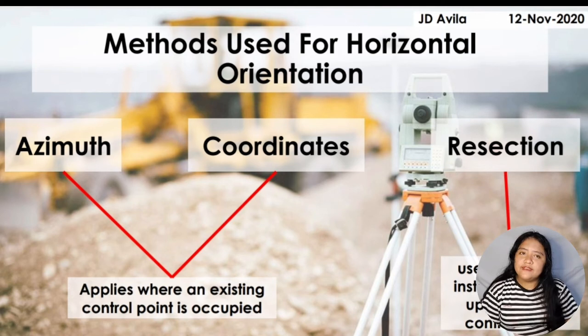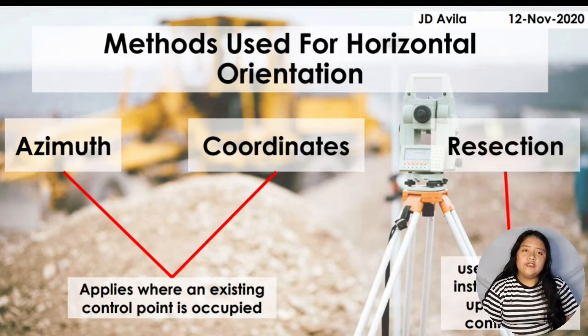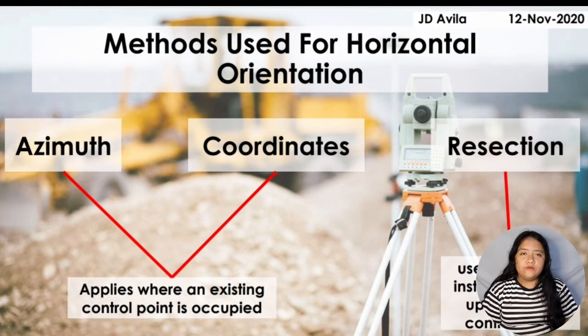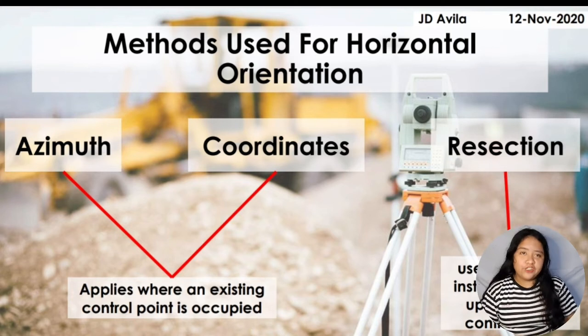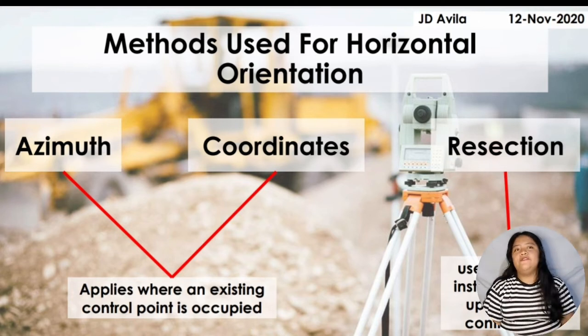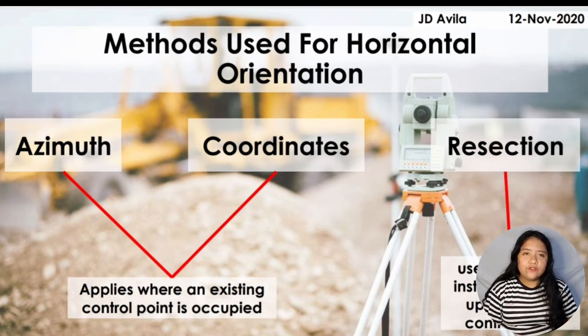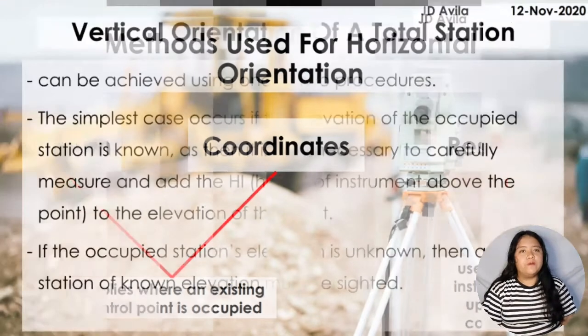If there is a discrepancy, the orientation procedures should be repeated. It is also a good idea to check orientation at regular intervals after stakeout has commenced, especially if it is a large project. In fact, if possible, a reflector should be left on a control point just for that purpose.